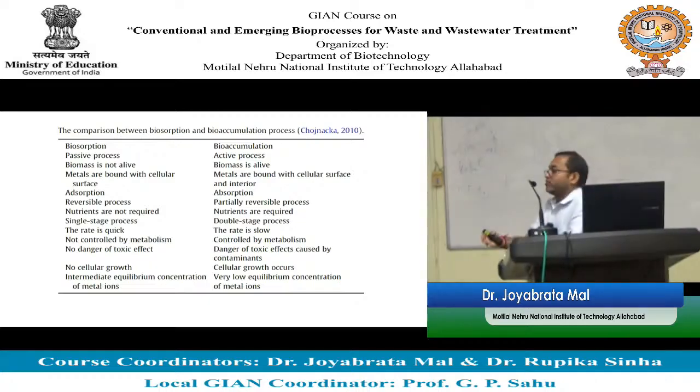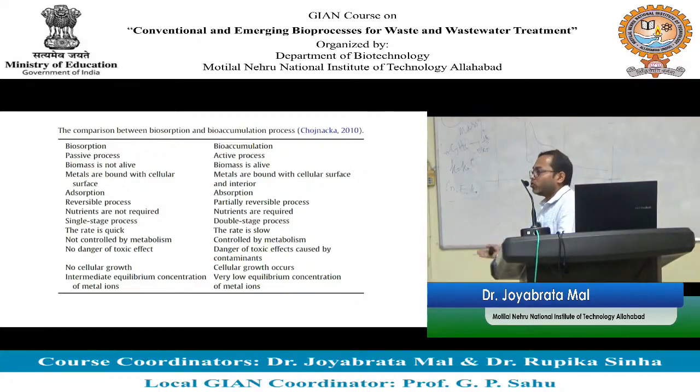Chromium is basically in bioabsorption, chromium 6 will remain as chromium 6. What if maybe after 2 hours, 2 years, it starts leaching? It will remain as chromium 6, isn't it? While if you reduce chromium 6 to chromium 3 and then immobilize, I mean chromium 3 can oxidize back to chromium 6 again, but that chance is much lesser than with the chromium 6 bioabsorption process.